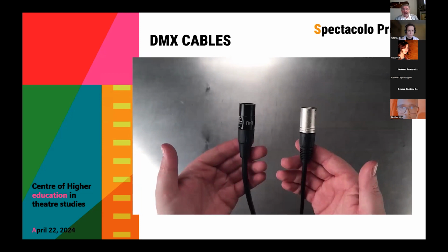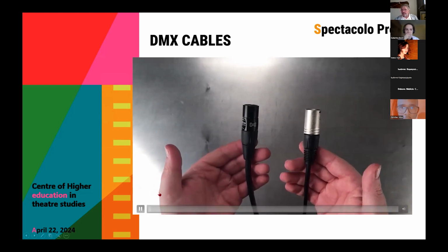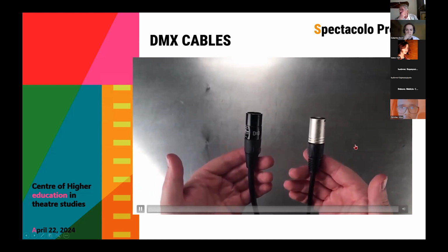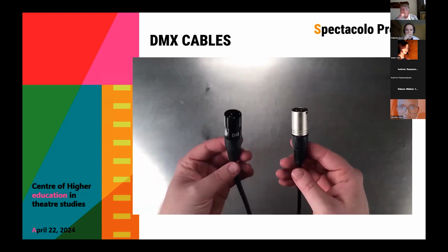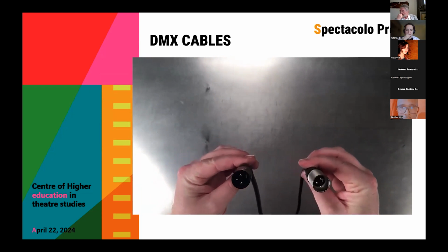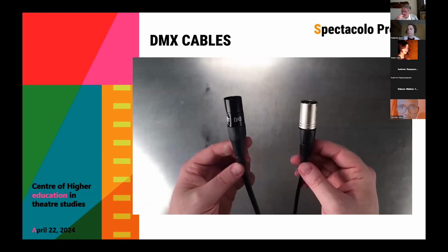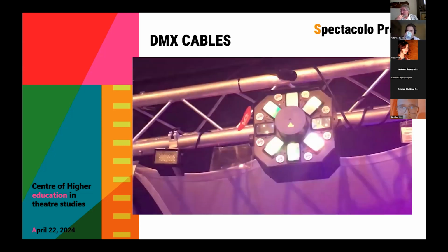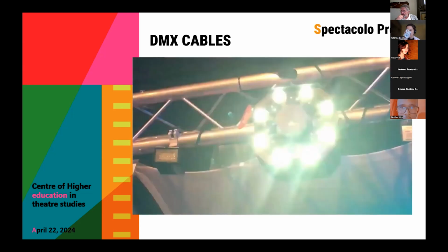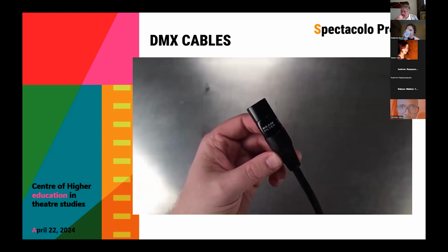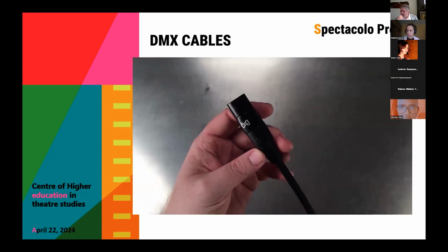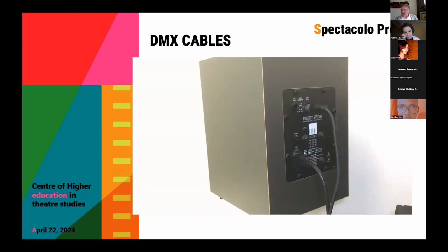Now, look at the video to see what the XLR cable for DMX function is. We appear to have two XLR cables that look pretty similar. Both have the standard 3-pin configuration and similar builds. Maybe even the connector is exactly the same on both. But go beyond the connector and you have cables with fundamentally different purposes. This is the XLR cable that we most often use for analog functions such as microphones and interconnects.